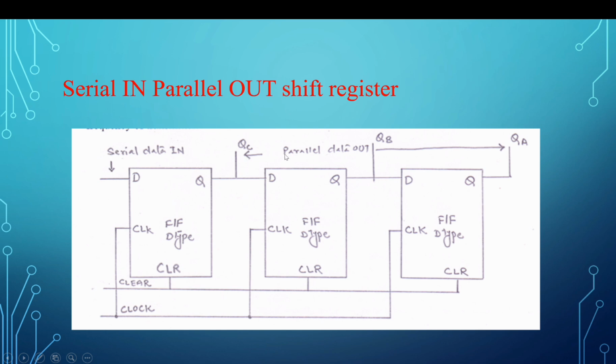This is called a serial in parallel out shift register. If your data size is 8 bits, 8 such D-type flip-flops will be required.